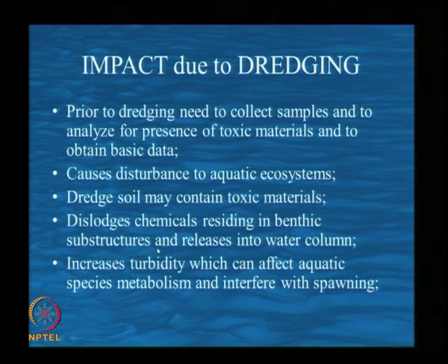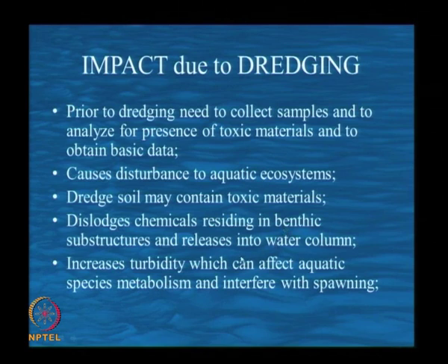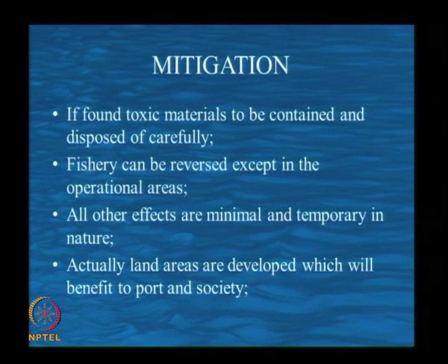This is about the benthic substructure. This is some fishing and other biofouling activity. Then it will increase the turbidity, which can affect the aquatic species' metabolism and interfere with the spawning. To avoid this, we will see that the dredging is not done during the spawning period. That is one activity which can be done to reduce the impact. So, toxic materials have to be contained and disposed of carefully.